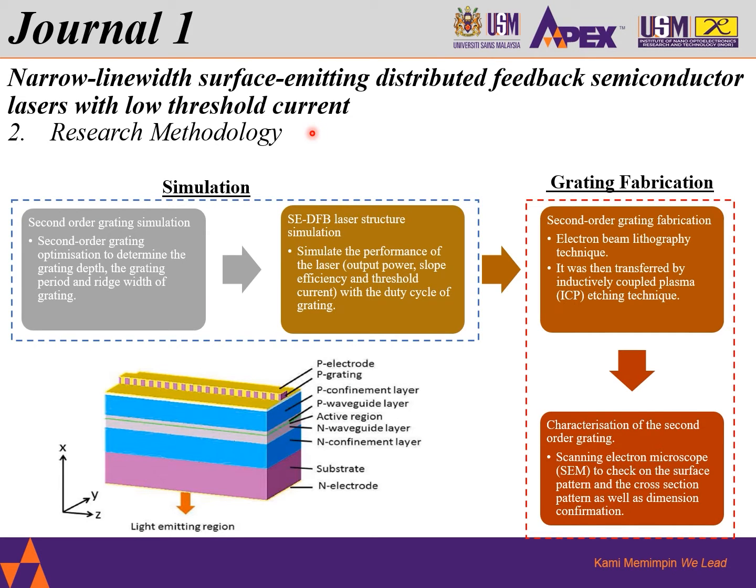Here is the research methodology or the process flow. It begins with the simulation by using software. It can be divided into two parts, which are second order grating simulation, which is to determine the grating depth, the grating periods, ridge width of grating. Next is the SEDFB laser structure simulations. This is to simulate the performance of the laser in terms of output power, slope efficiency, and the threshold current with the duty cycle of the grating.